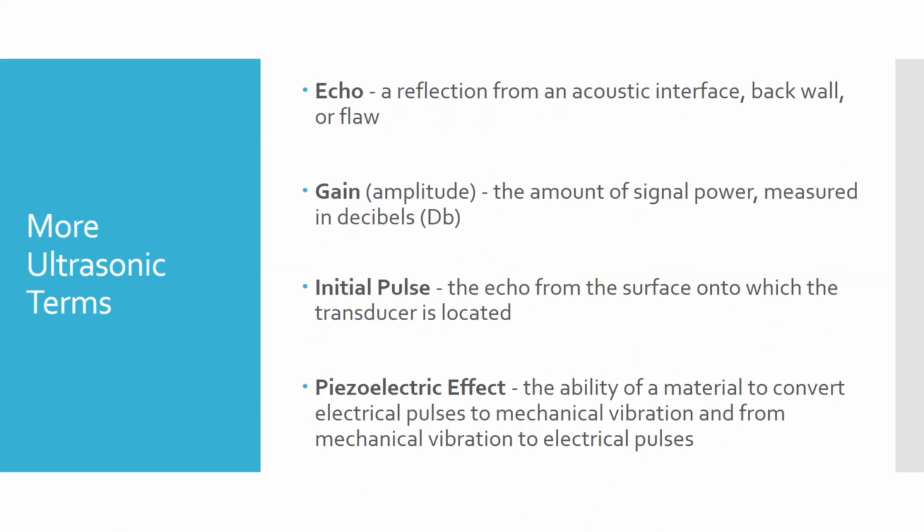And then in a good part like I have here, where there's no cracks, this sound will hit the back wall and it'll bounce back up to the top. So that's a back wall echo reflection. So those two are kind of non-relevant indications. We use them when we're calibrating the equipment, primarily to calibrate the speed of sound that we're experiencing on that day. But you will get that initial pulse, and that blocks a certain amount of ability to see directly in front of the probe.